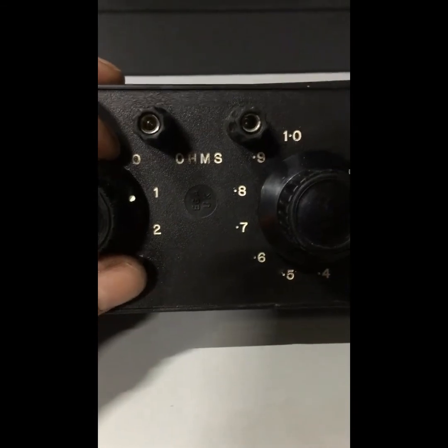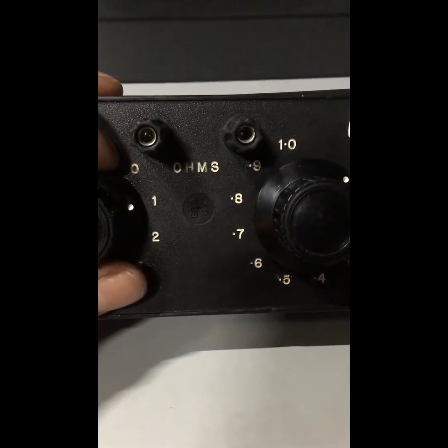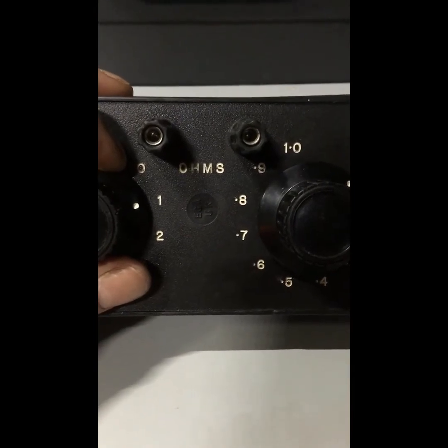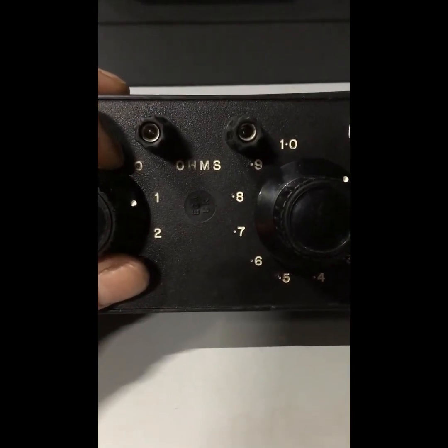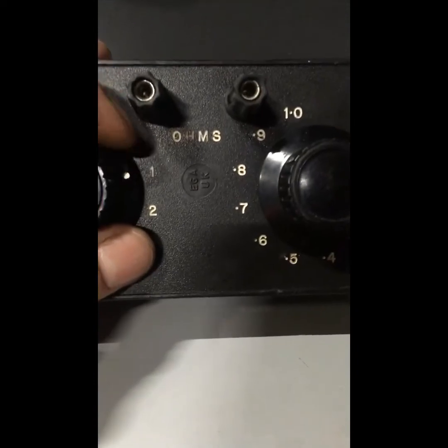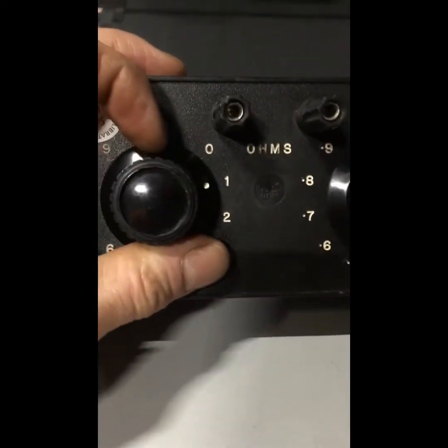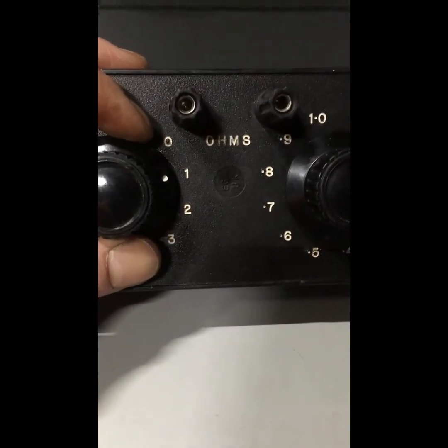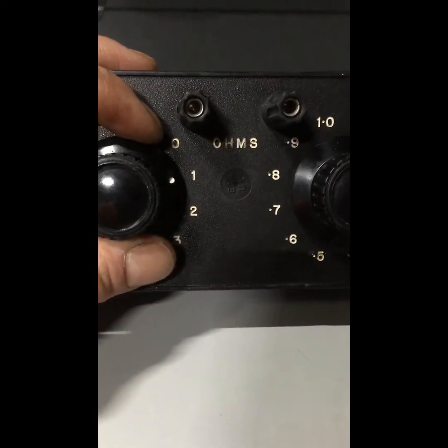Obviously, the higher the voltage on the feed of the track, the lower the shunt, and vice versa. So it's a good rule of thumb that. If the voltage goes down, the shunt goes up. If the voltage goes up, the shunt goes down. We don't want the shunt too high or too low. We're aiming for that perfect 1 ohm. And we also have a minimum setting. We also call that 0.5 ohms. We don't want to go below that.